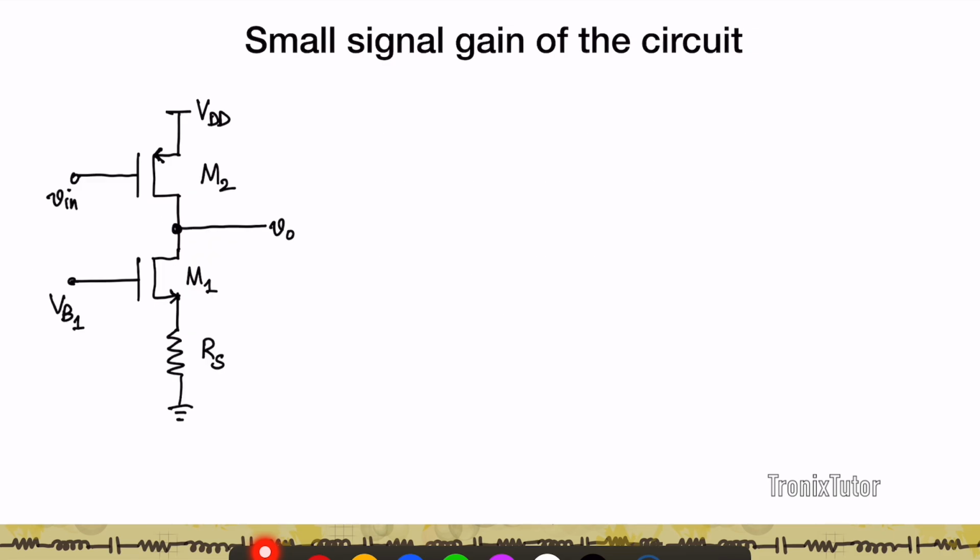Now let's look at another circuit here. So here again, as always, let's first identify what stage this resembles. So again, I have a circuit where I have a transistor. The input signal is applied at the gate of the transistor. The output signal is pulled from the drain of the transistor. So this has to be a common source amplifier.